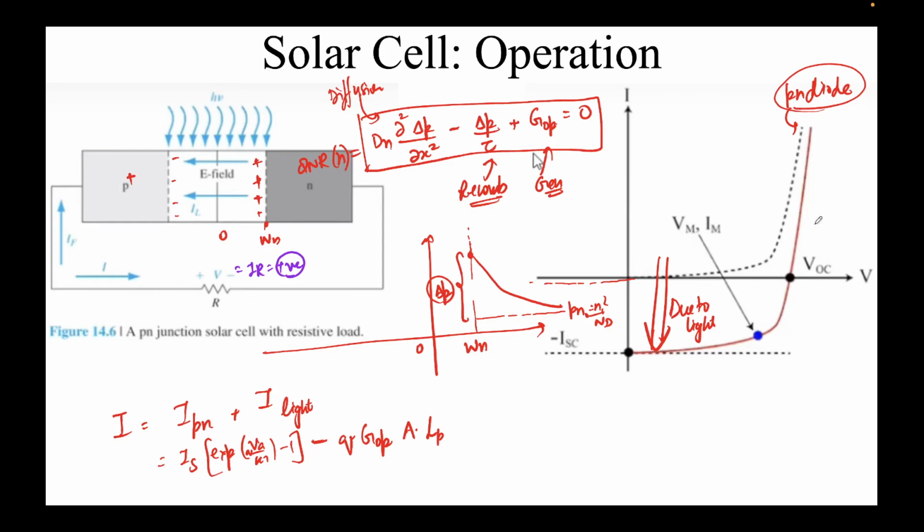If you apply very high bias, let's say 5 volts or something, you're essentially going into the first quadrant. So there you lose all the peculiarity of the light, because there IP and this exponential term will significantly start to dominate whatever this optically generated current due to photons is. That's why we restrict ourselves to the fourth quadrant. The self bias, I hope I have explained.